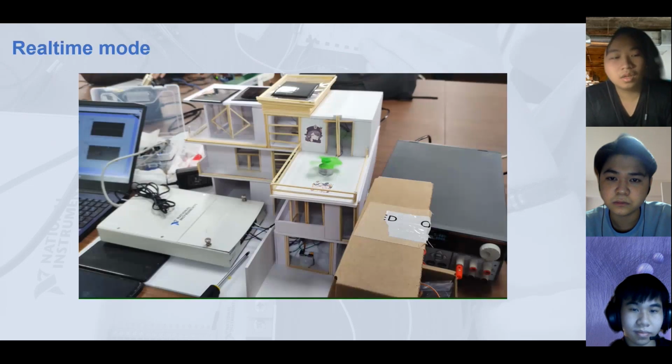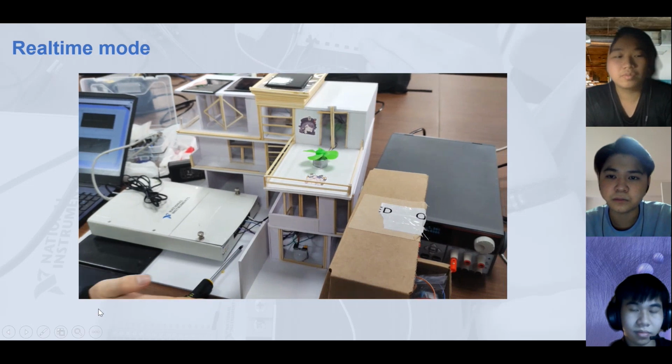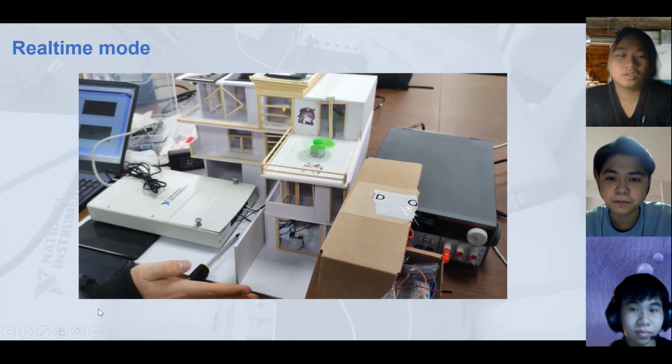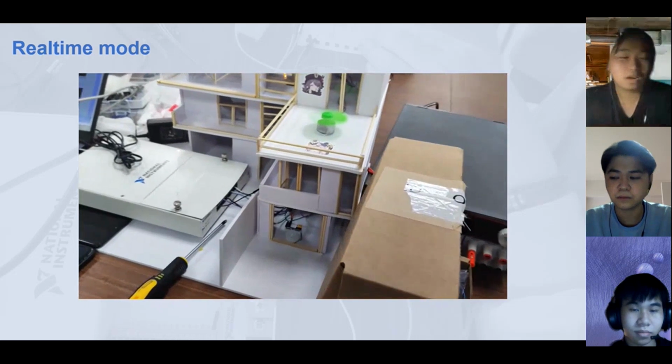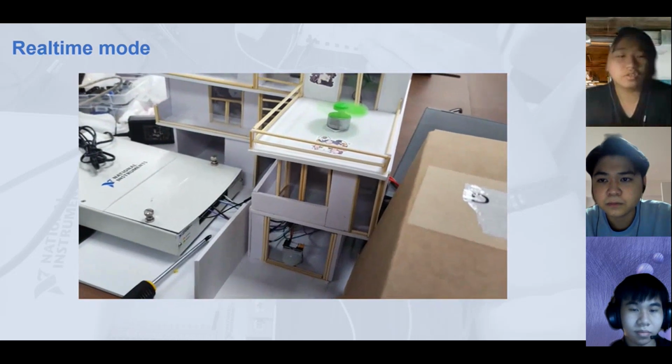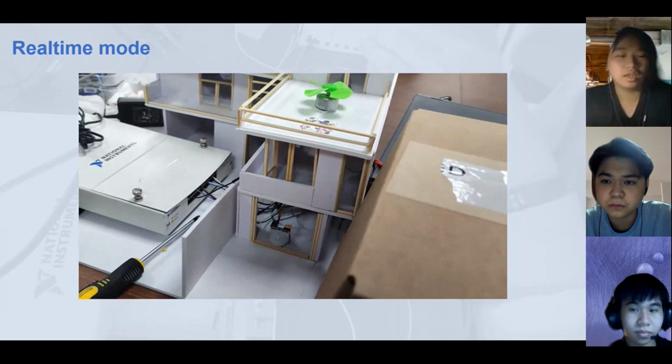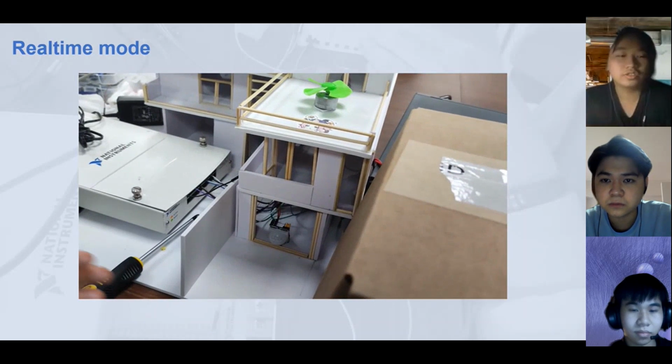Example. To run the program in real-time mode, make sure the USB 6255 device is connected and configured in LabVIEW mode. Next, navigate to the Configuration tab, select the device and PIR channel, then click on Run. The program will automatically start in real-time mode.